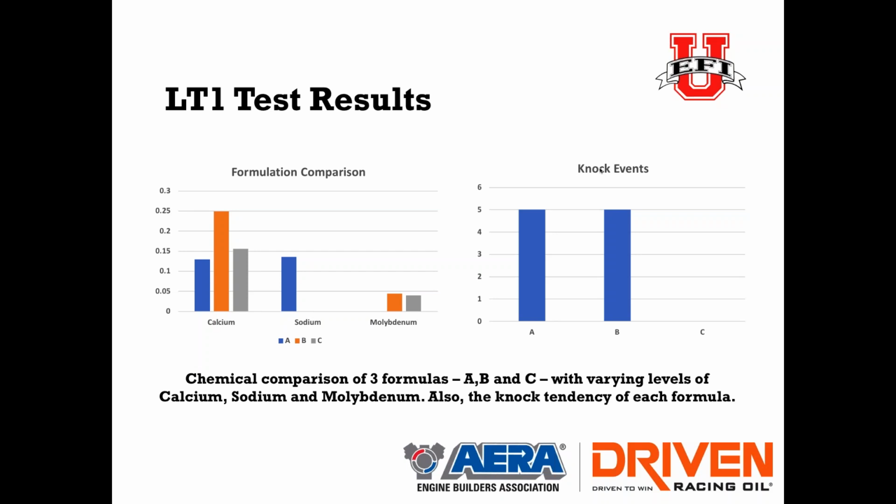Taking the same base oil, we took the sodium out, increased the calcium, and added some molybdenum, which acts as a suppressant, and still had 5 knock events. Then we brought the calcium level down, not quite in half, kept the moly in there, and all of a sudden, no knock events.